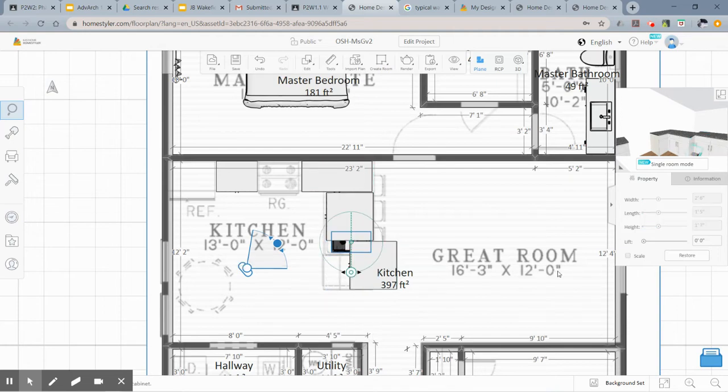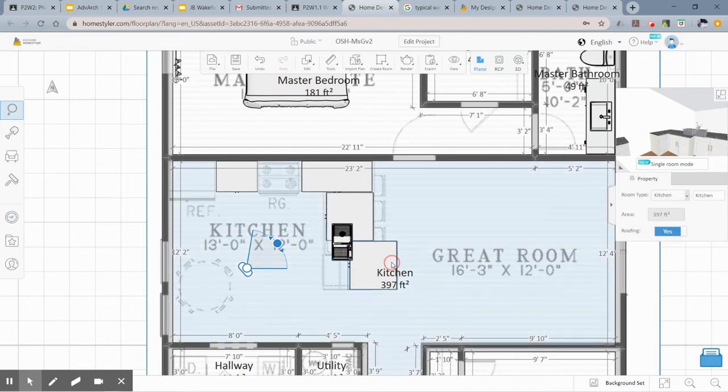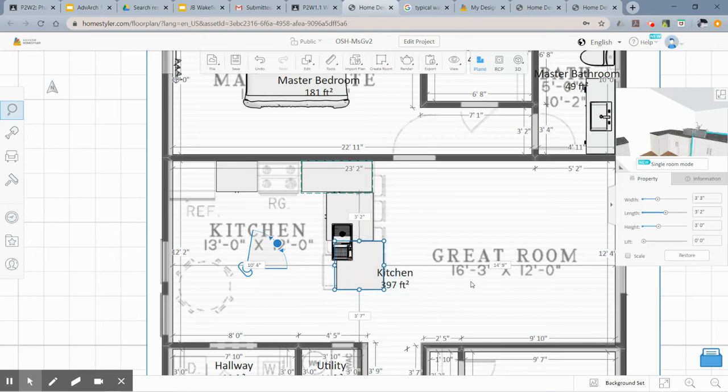Yep, there it is. If you click on this, you're going to see that the height is 3 feet. So I'm going to set this sink's lift at 3 feet, which is the same as its height off the floor. And there, now it's sticking out. I'm going to rotate it so that the neck of the sink is at the back, and move it forward like it is in the original layout. And now I'm going to move this back into its place.